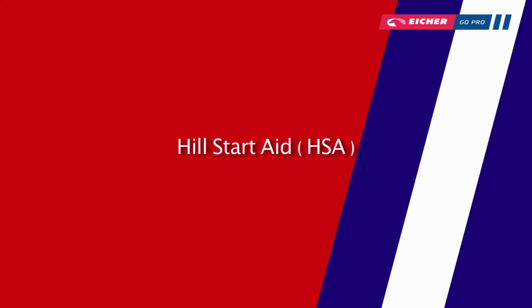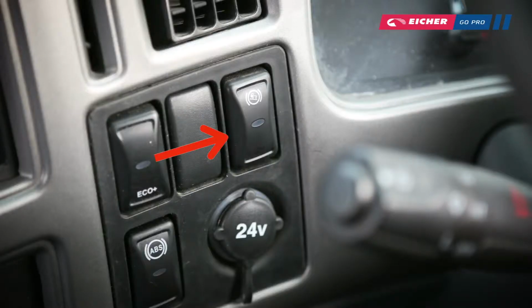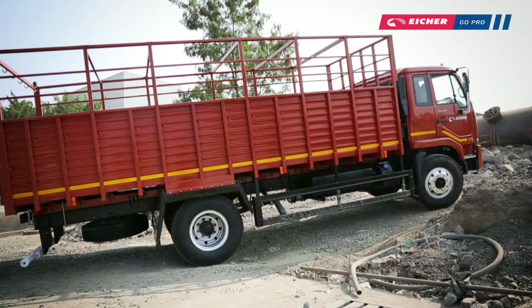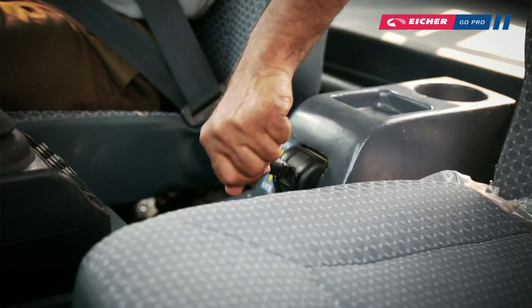It ensures optimum acceleration to complete overtaking in minimal time. Hill Start Aid, HSA function: to support the drive-off of a vehicle, for instance on a grade, by holding the vehicle until the engine develops enough torque to propel the vehicle after a certain time. HSA switch: it is placed at the left side of the steering column below the instrument meter. If we are on a gradient, before launching the AMT, press the HSA switch and release the handbrake.